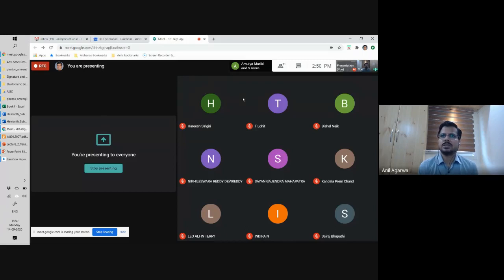So your service limit states are the kind which are only causing you some kind of a discomfort, or your functionality is not satisfied. So you want a floor to be flat. You don't want the floor to have a slope, or a slope large enough so that your chairs start to slide. Like if your chairs have rolling wheels, then the chair should not start to move automatically on the floor, just because the floor has so much of slope. And likewise, but as soon as you remove the loads, the floor will go back to its horizontal position, and then the structure is usable.